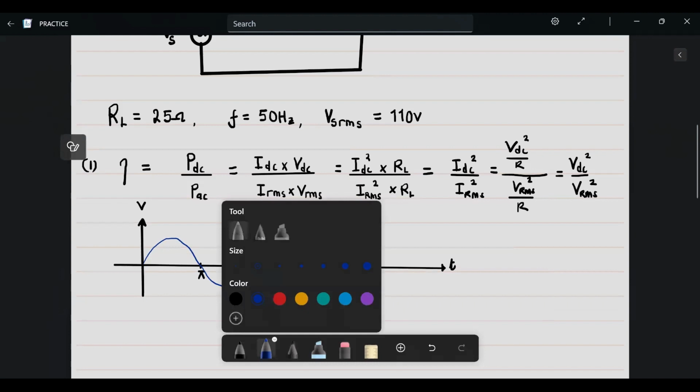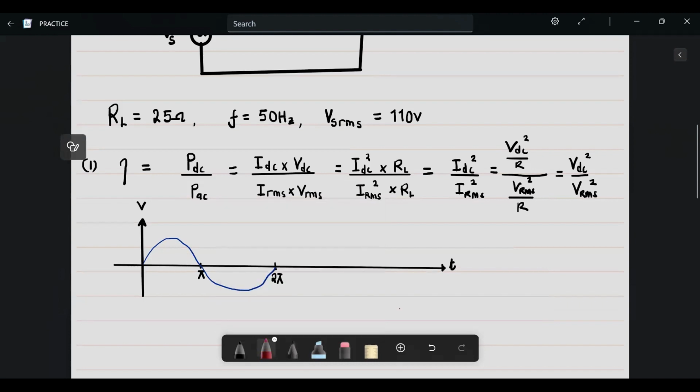It looks like that. And then the output voltage cuts off the negative cycles, right? So the output voltage will end up looking like this. During the negative cycle, it will be off. And then it will come on like that also during the other period, and then be off. So if you notice, the total time period for this one is 2 pi, right? That's the total time period. So period is equal to 2 pi.